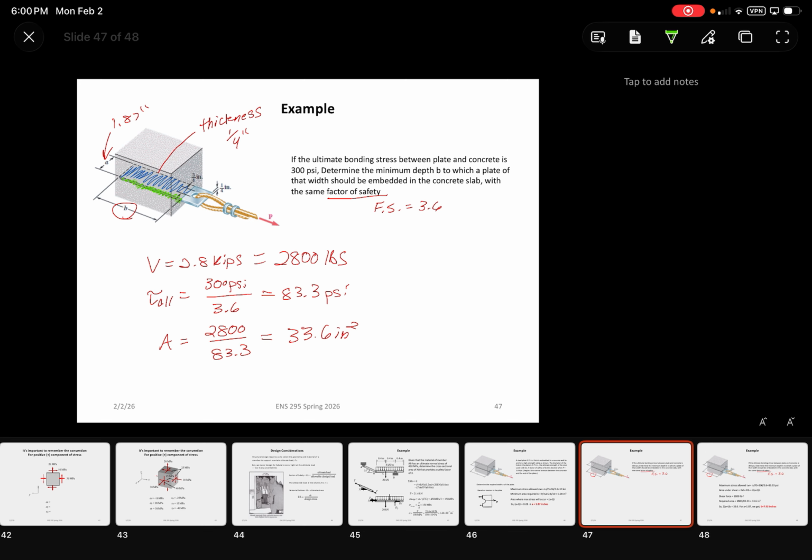All right. Now, most times for concrete, you would generally just consider the shear planes. In some instances, if you're using a special grout with a tensile strength, you could also consider some type of net stress here, but we're ignoring that for simplicity of this problem. Things can get pretty complicated really quickly when you start considering all the different stresses and forces acting on certain things.